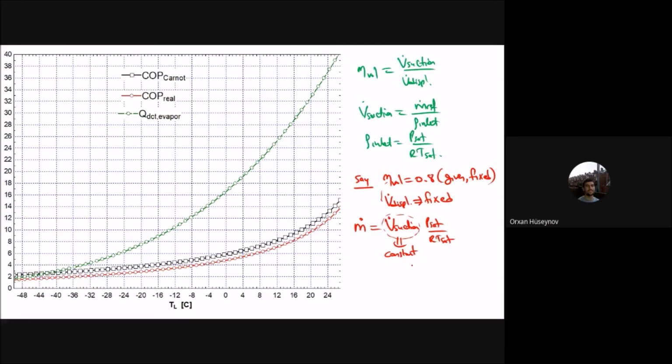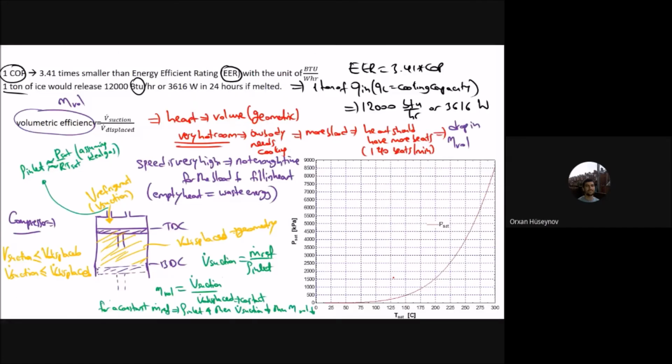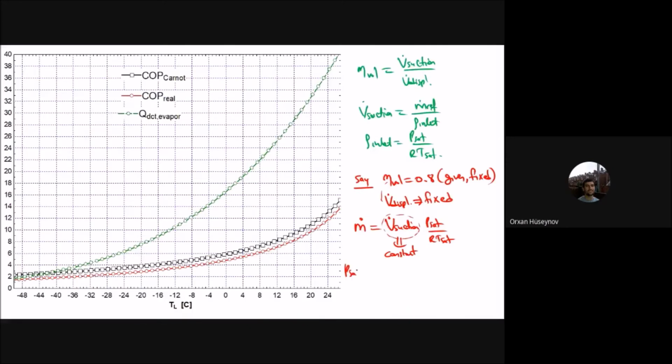Okay, now let's see the chart as in the previous case. We can see that, for example, if the saturation temperature rises from 25 degrees Celsius to 150 degrees Celsius, a temperature change of this amount, the pressure change is very huge. You can see that it is 500 kilopascal. A huge pressure change with respect to a small temperature change. Okay, so Psat changes faster than the Tsat.